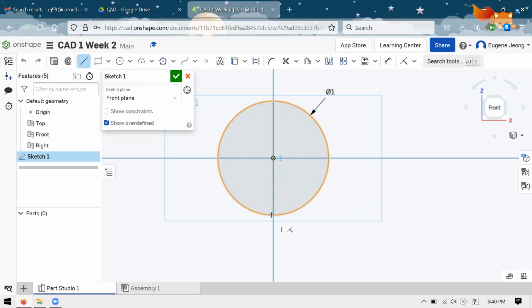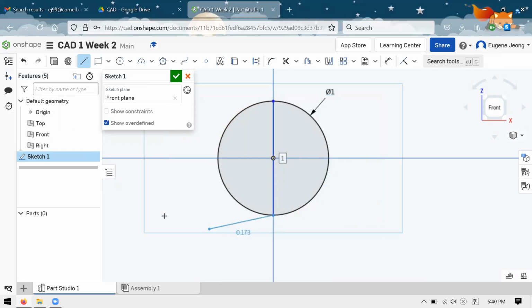So what I want you to do is just on any plane, create a sketch, create a circle. And what I want you to do then is to create a diameter of the circle. So you can go to your line tool, hover over the top center of your circle, make sure it turns orange, click once here, and hopefully it'll snap to knowing that you want the diameter. If you click on the right spots, it'll do it automatically for you. If not, hopefully you're able to use what you know about constraints to tell it that you do want it to be the diameter.